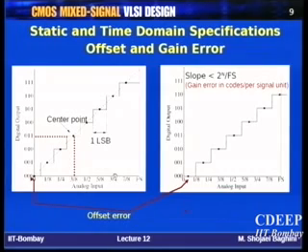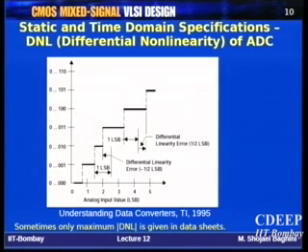When we talk about offset error and gain error, we are not looking at what will happen for a particular code, for example at 100 or 011 or something else. We are looking at the overall performance of the ADC. But now, with DNL and INL specifically, we are looking at the code by code or bit by bit performance of the ADC. Eventually it is the same thing.